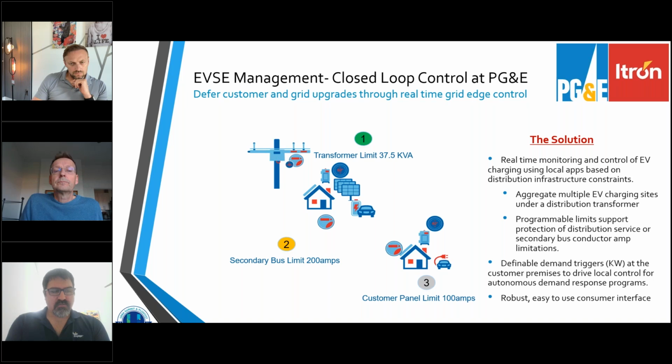So in coordination with PG&E, and part of what we did with PlugFest, how do we put this in action? Clearly, as we mentioned, the battleground associated to why the technology has been innovated is the interaction between utility and consumer, and the gaps relative to playing whack-a-mole, trying to chase down every new EV customer that pops up on your grid and making sure the infrastructure you have is ready to accommodate that new load. And so PG&E's concept was, if they could leverage some rulings in the National Electrical Safety Code that allowed for real-time automation to throttle controllable loads to keep customers within their panel limits and service conductor and transformers within their limits, then twofold benefit.